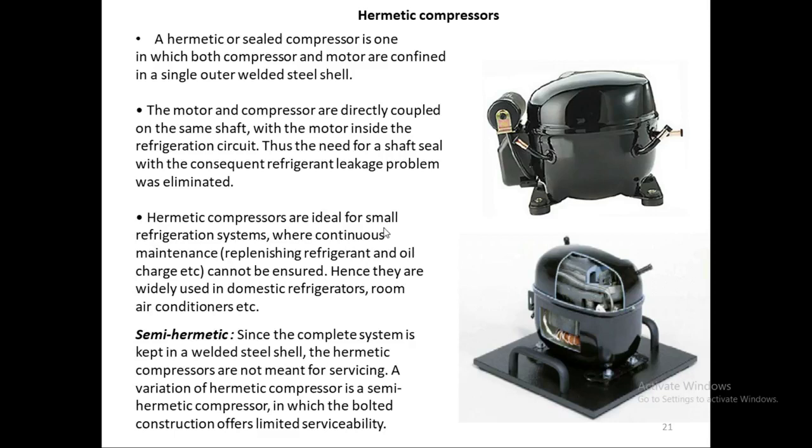So hermetic compressors are ideal for a small refrigeration system where continuous maintenance or replenishing refrigerant and oil charge etc. cannot be ensured. Hence, they are widely used in domestic refrigerators, room air conditioners. The lubricant which is required by the moving parts of the compressor is also inside this compressor.